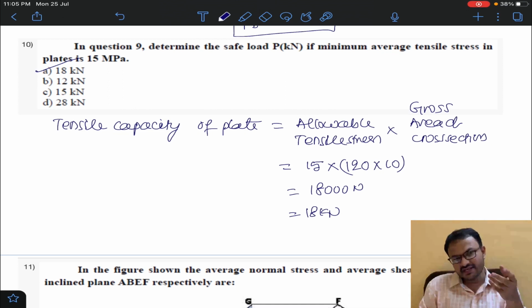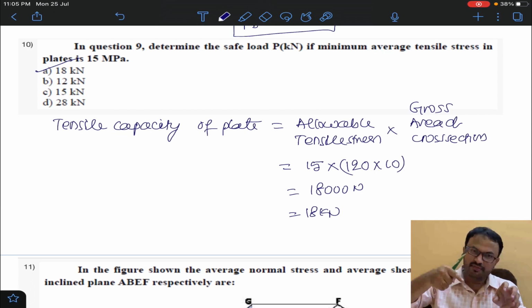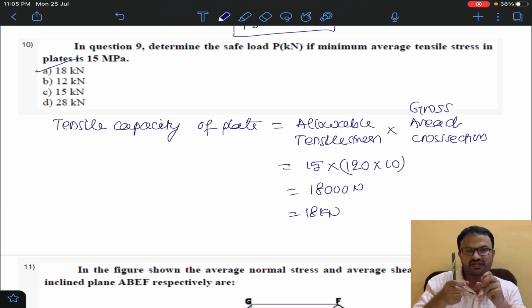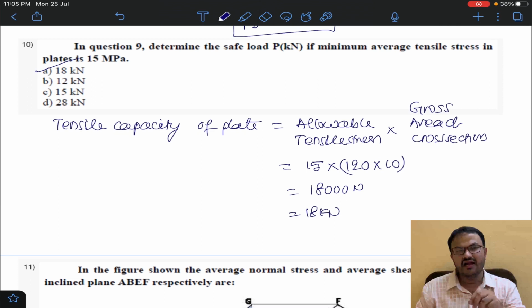Similarly, the bearing capacity can be calculated by multiplying diameter and thickness of the plate. That inside portion will be having some bearing stress, that is bolt portion having some bearing stress. So bolted inside area is diameter into thickness and allowable bearing stress. This is bearing capacity of one bolt. Similarly, how many number of bolts into N.